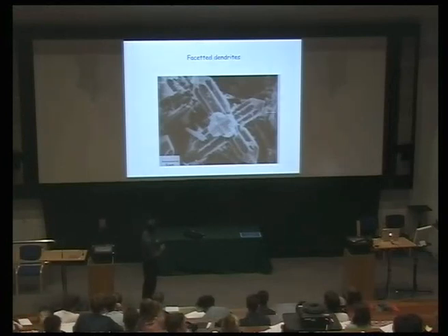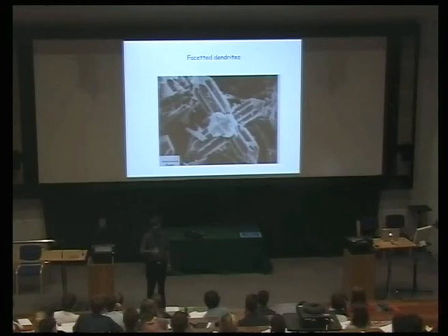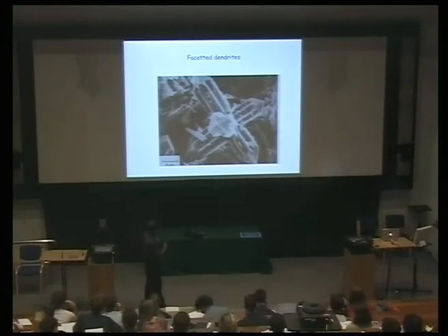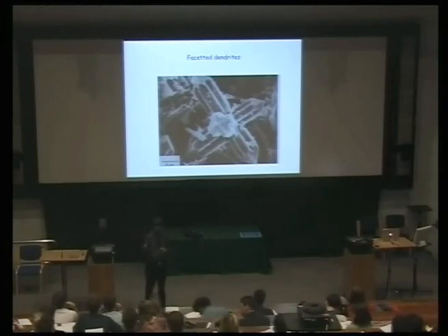Okay? And you can see it is highly faceted, because in this case, the interface energy is strongly dependent on the orientation of the interface. So these, for example, are the 100 planes of the dendrite. And this dendrite grows rapidly along the 100 directions. This is what I was telling you earlier, that in cubic systems, systems with lattices which are cubic, the fastest growth direction is 100.